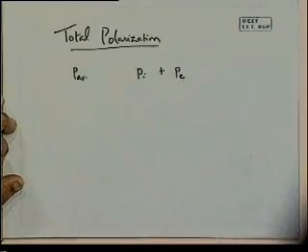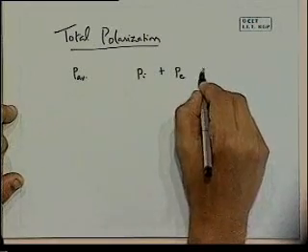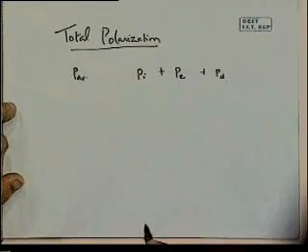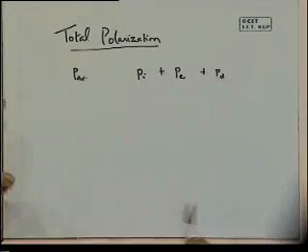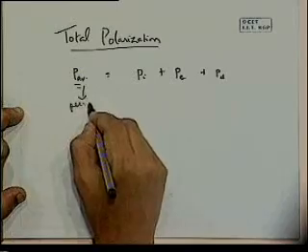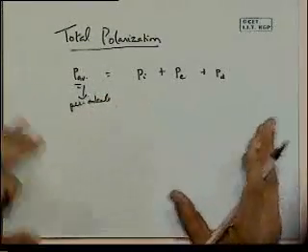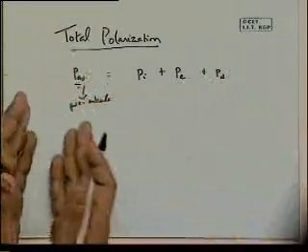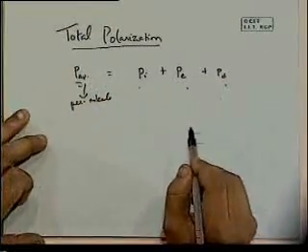And to some extent we can include even the orientational or dipolar effect. But we have to leave out the interfacial. We can't just add that on, because this is an average value per molecule. Remember that, the dipole moment per molecule. Now, it depends on the particular nature of the grain boundary and also I can't simply add it on here. But for these, we can more or less deal with it.